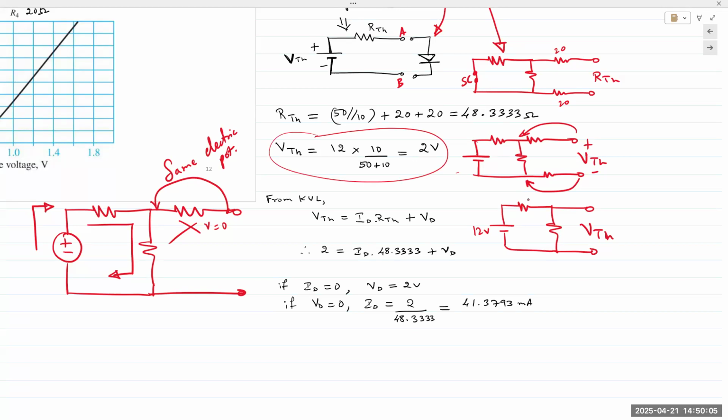It's the voltage division principle. Is that something you studied in 115? Perhaps. Okay, that's good. So 12 times 10 over 60 gives us 2 volts. So the diode is seeing an application of 2 volts as the source because it's being broken down across 4 resistors. So by the time it reaches the diode, it's already down to 2 volts.